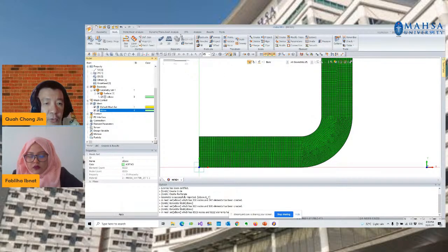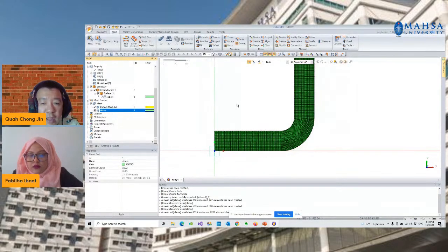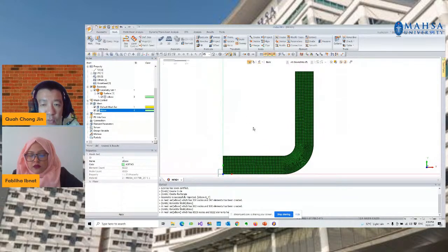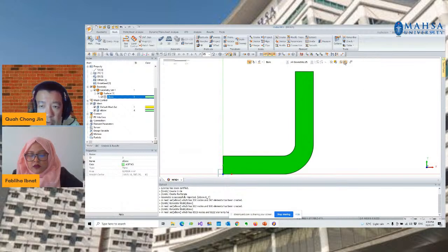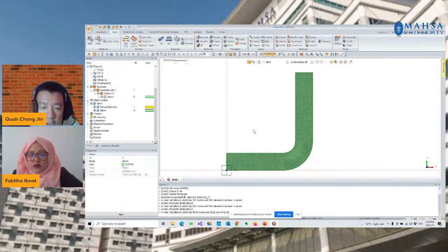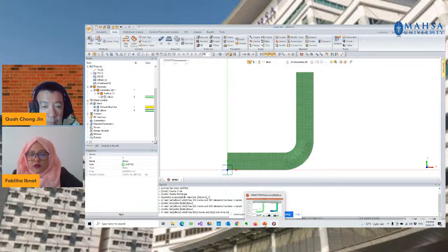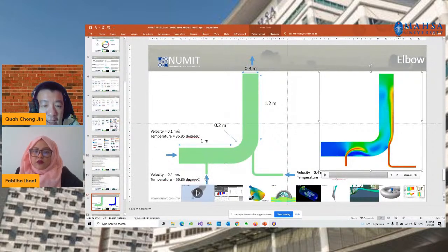And the next thing to do is very simple. We have to know what the boundary conditions to determine are. In our case, we have the wall of the pipe itself. We have the inlet section over here, and we have the outlet section. Now we'll be doing a different case study compared to our PowerPoint, where we have an extra 2 inlets, right? So I'll just show you the workflow, then we will add on the next inlets.